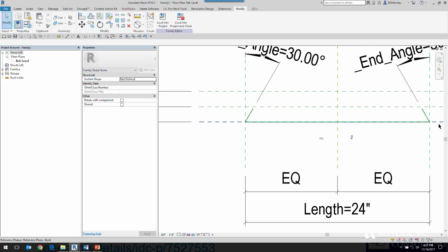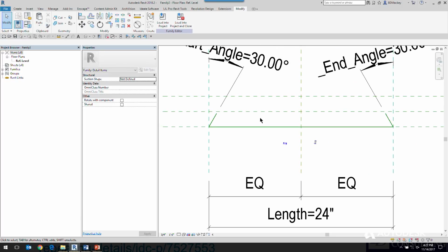So that's one of the big things for me. I also have one that started with basically just a filled region going through here. And then I just do a save as, now it's steel. Now I do a save as, now it's wood. Save as, change the hatch pattern, now it's concrete. So once you get one set, you can usually do a save as rather quickly and start busting through a lot of those line-based detail components that you would want.